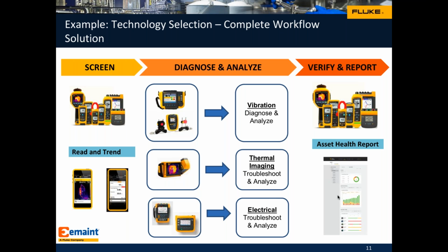So you would often have a screening tool, which could be a simple tool. Then you can move to having diagnostic tools. So often we think about vibration, or you can think about power quality. You can capture the data, but those are much more for experts to look at, as well as a power logger and thermal imaging. Thermal imaging could be as much a screening tool as a diagnosis tool. There are various levels of thermal imaging, from level 1 to level 3, depending on the experience.